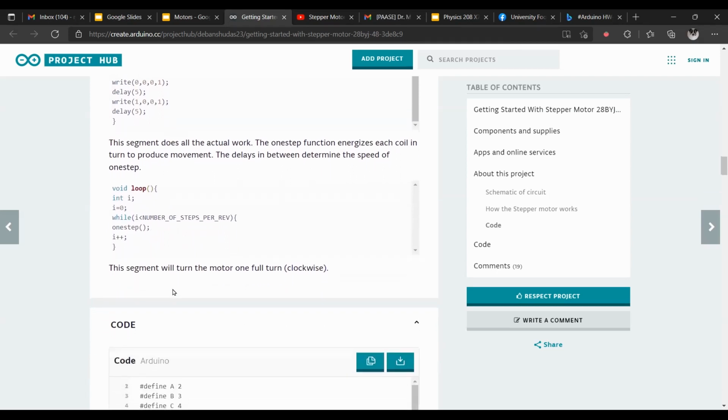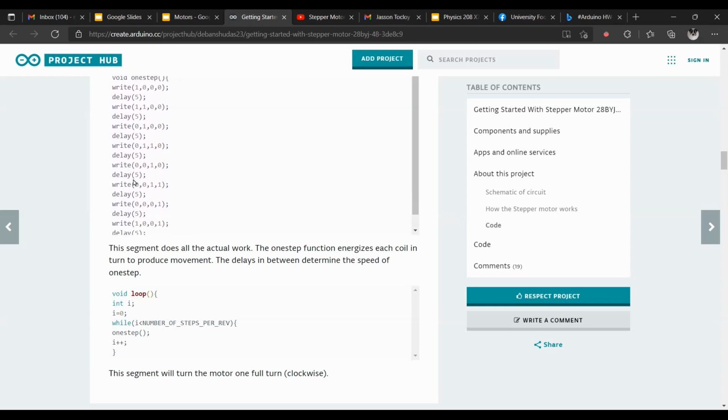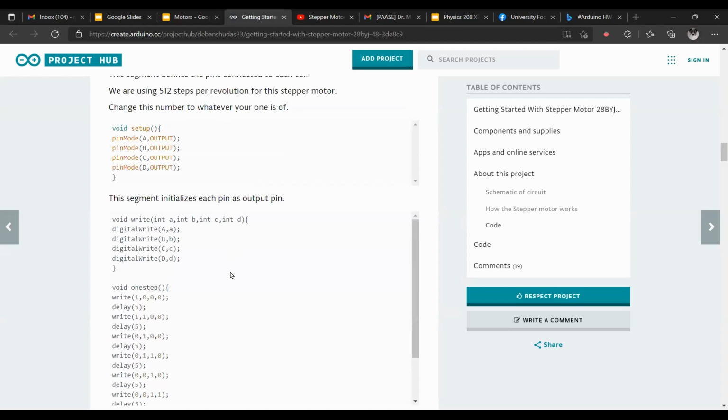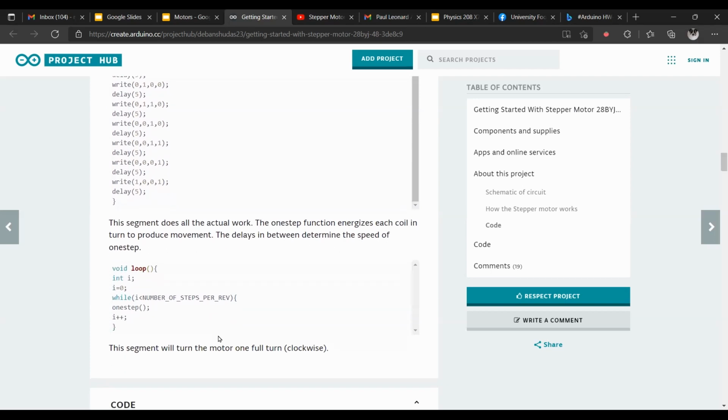Now, essentially, because of the gear reduction, you would need, it's explained in the YouTube video in the succeeding, you would need to do this full number of steps by 512 times. I believe it's 512 times, tama ba? Yeah, 512 steps per revolution. You need to do this full sequence 512 times so that the shaft will move one full 360 degrees. Okay? One full 360 degrees.